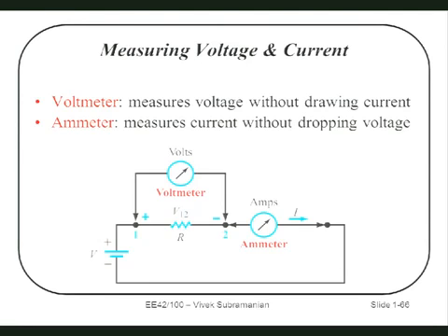Voltmeters, or ammeters for that matter, have similar things we need to deal with. Okay, so, if I want to measure the voltage across this resistor, and I put a voltmeter across it, what property would I want that voltmeter to have such that I don't mess with the resistor? Yeah, I want it to be really, really high resistance. Ideally infinite resistance.